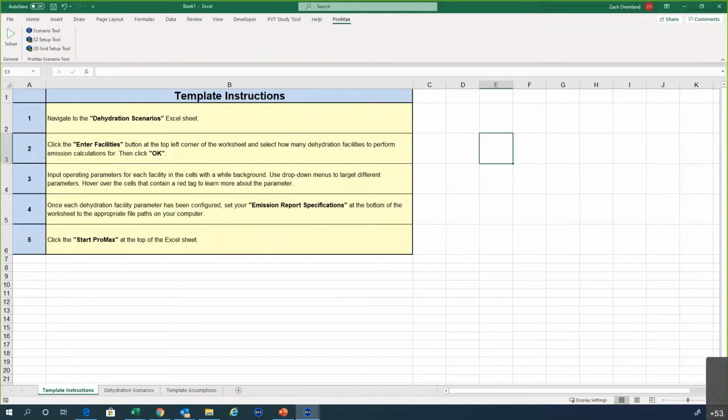So someone asks, are we still concerned about emissions calculations if the vapors are going to a flare? The answer is yes. Even if you have a control device, from my understanding, and for those of you who get into this a little bit more, correct me if I'm wrong, you still, in certain situations, have to report uncontrolled emissions. So let's say that flare were to not be operating properly or be taken down for maintenance, whatever it might be, you still have to report what the uncontrolled emissions would be. So that's what our tool will do. If you do have a flare, it will show you what those controlled emissions are, and it will also show you what those uncontrolled emissions are as well.